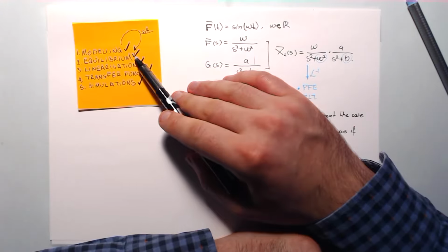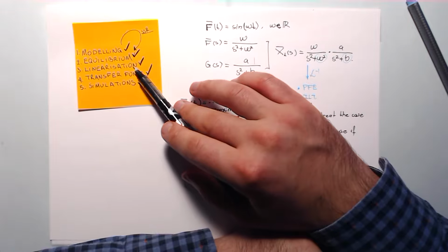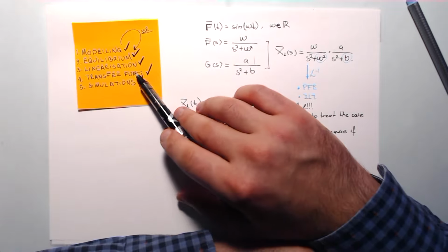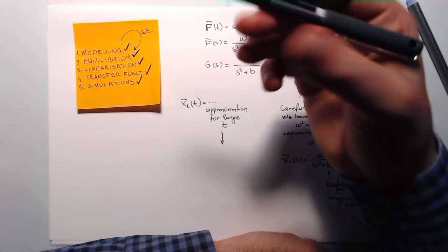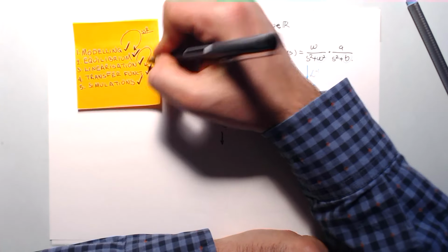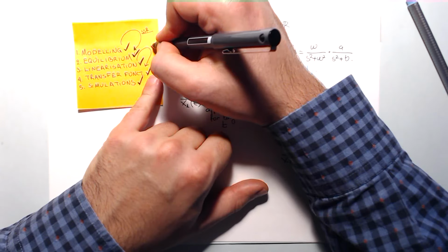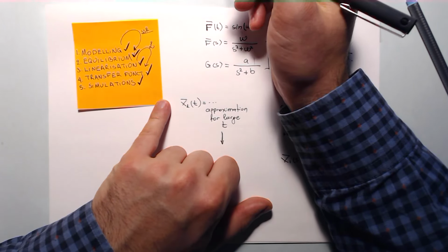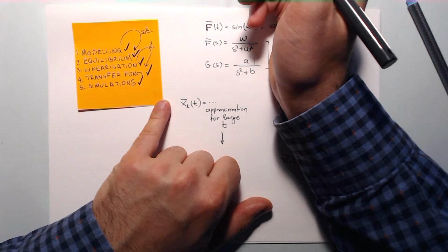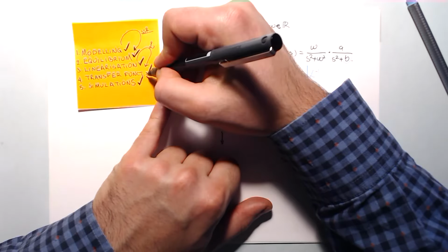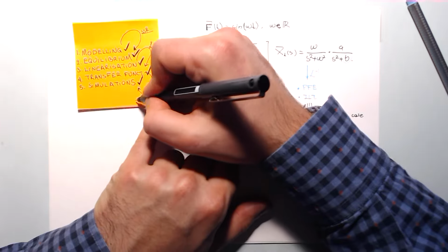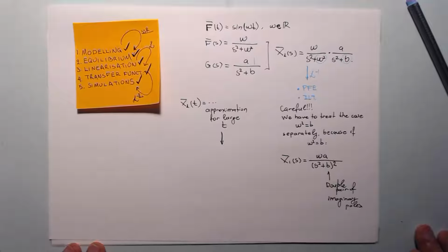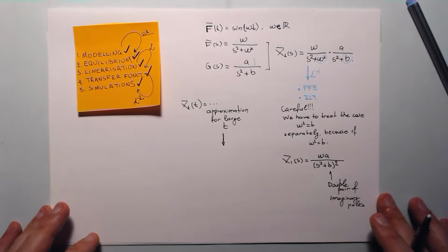We determined the equilibrium points. We linearized the system dynamics. We took this linearized dynamics and determined the transfer function by applying the Laplace transform. So to go from the linearization to the transfer function, we used the Laplace transform. And then we simulated the system starting from zero initial conditions using the inverse Laplace transform. Starting from zero initial conditions goes without saying, of course.